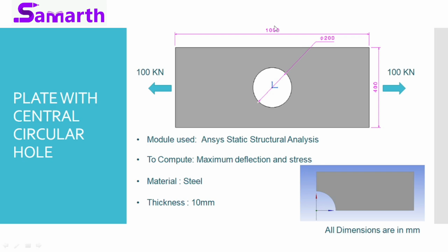Okay, you can see this is the complete model. It is axisymmetric about the y-axis and axisymmetric about the x-axis. Here in this problem, we'll take 1/4 of this model, which is nothing but the axisymmetric model, in order to reduce the computational time of solving this problem.